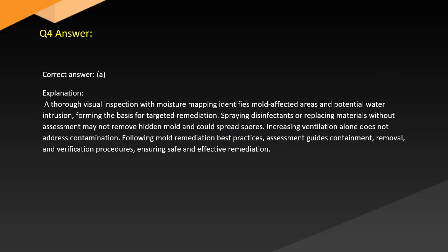Answer. Correct answer: A. Explanation. A thorough visual inspection with moisture mapping identifies mold-affected areas and potential water intrusion, forming the basis for targeted remediation. Spraying disinfectants or replacing materials without assessment may not remove hidden mold and could spread spores. Increasing ventilation alone does not address contamination.